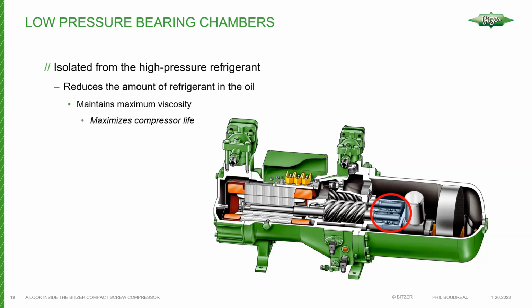But generally, what you'll do is close off the suction service valve completely, open it up one turn, and just give the compressor a split second to turn over. Having a gauge on a low pressure port of the compressor will enable you to look for that gauge deflection in a downward manner. So we want to see that pressure drop.